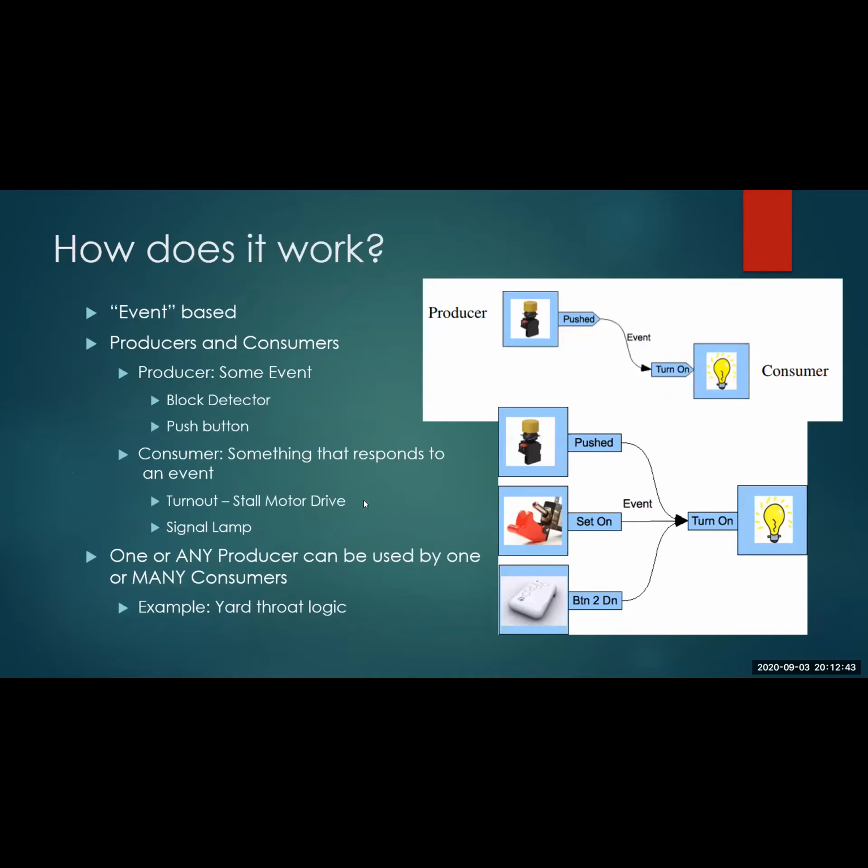All right, moving along here. How does it work? The whole thing in LCC is they have this thing called events. That's kind of a buzzword, I know it's a new term, but an event is something that triggers an action. For instance, maybe a wheel is detected because it's hitting a detection block. That creates an event, and that's broadcast over the entire layout.